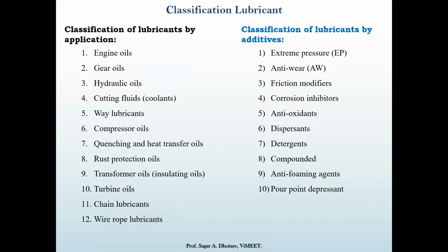Based on the additives, there are 10 types: extreme pressure, anti-wear, friction modifier, corrosion inhibitors, antioxidants, then dispersions, then detergent, then component, then anti-foaming agent, and pour point depressants.